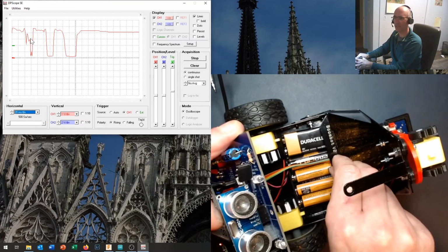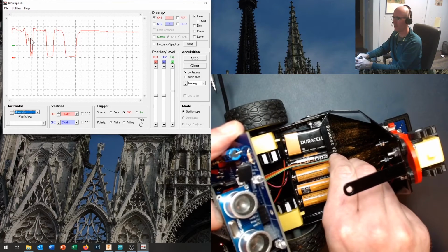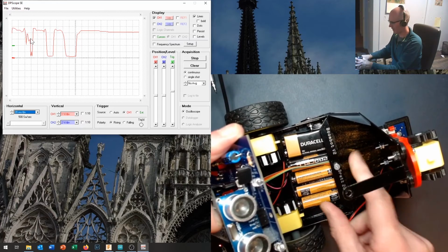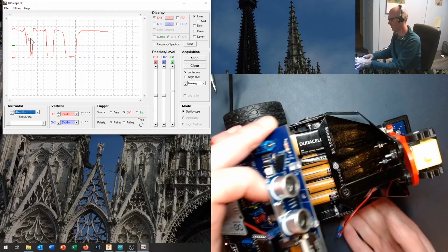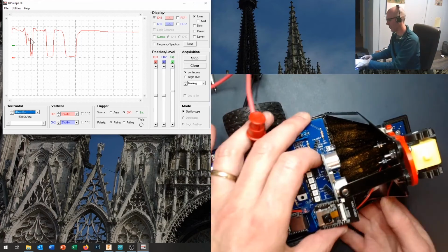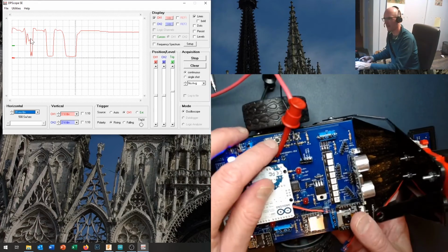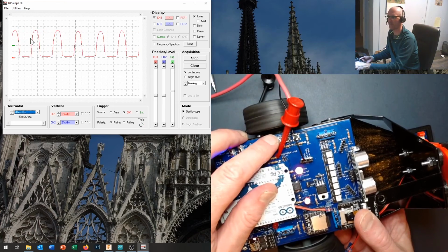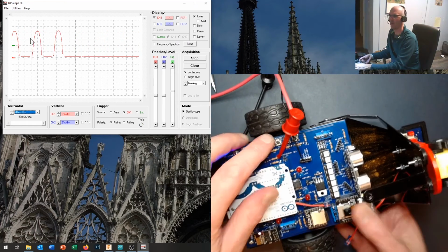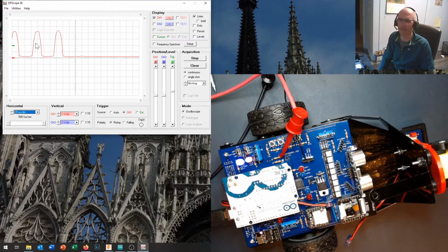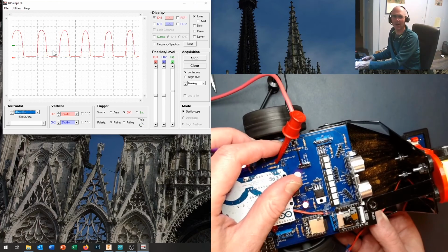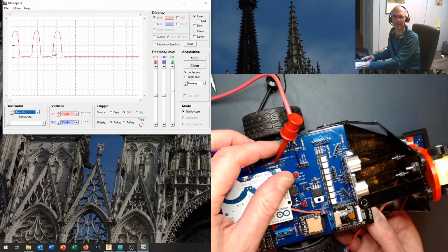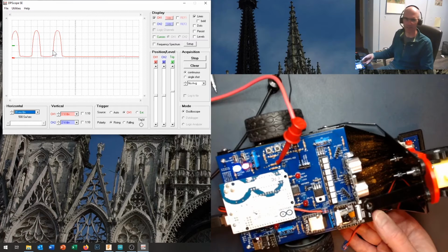Now you could use a combination of nuts, spacers, whatever you need to get the bottom of this board the exact right height off of here so that you can see when it spins that your signals look nice and clean like that. Okay, see the difference between having your board at the right height and having your board at the wrong height? Nice clean signals versus ugly signals.